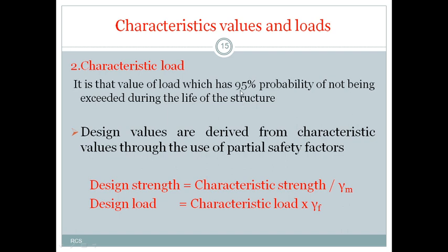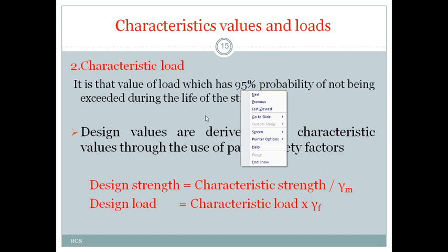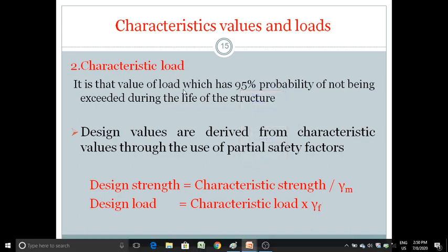So what do you mean by this? The load that is estimated at the time of design of a structure, at any time during the life of the structure, should not exceed that estimated value with 95% probability. That means there is only a 5% chance of exceeding that estimated load throughout the life of the structure. So that is the meaning of characteristic load.